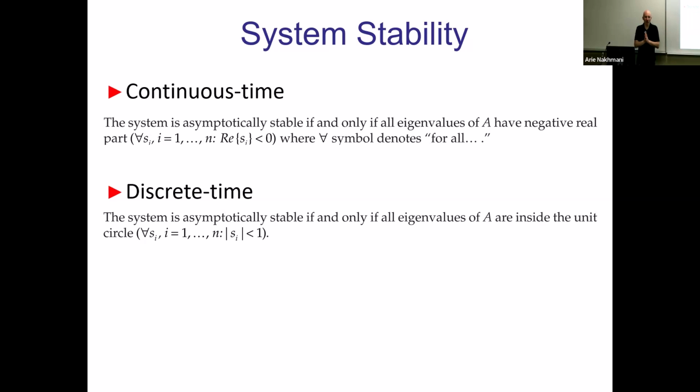All right. So if all of the eigenvalues of matrix A, and pay attention that for SISO or MIMO systems, A is still an n by n matrix, same matrix practically, right? Regardless of the number of inputs and outputs, A is still n by n, dependent on the actual physics of the system. So I'm just replacing poles by eigenvalues and claiming exactly the same theorems. This is what we have here. So if all of the real parts of the eigenvalues of your matrix A are less than 0, which means left semiplane, then it is asymptotically stable.